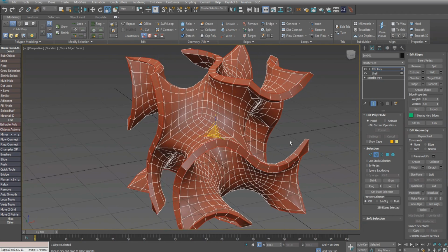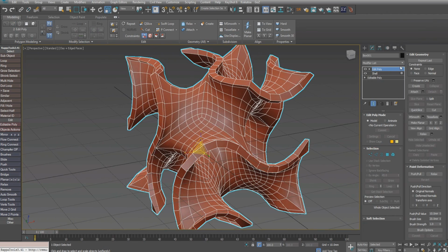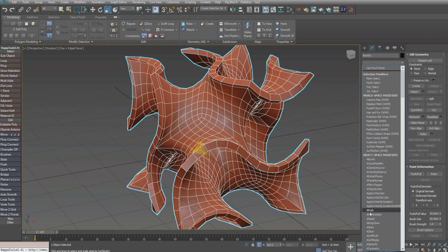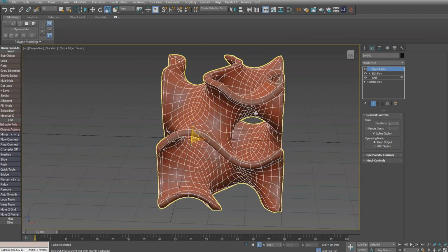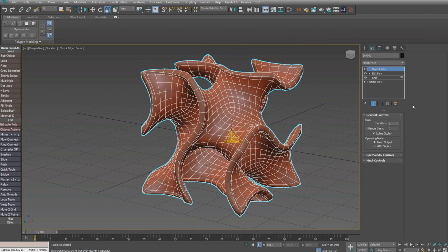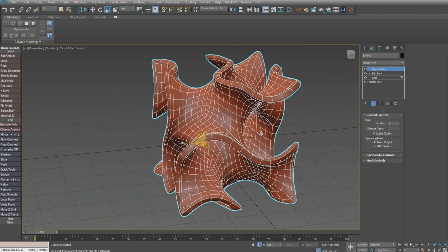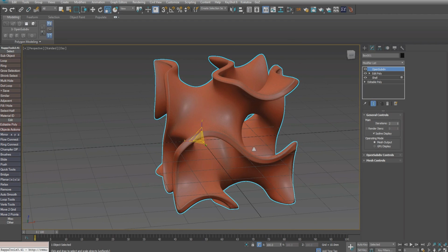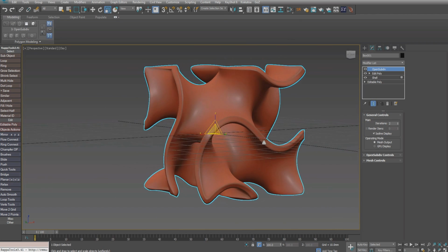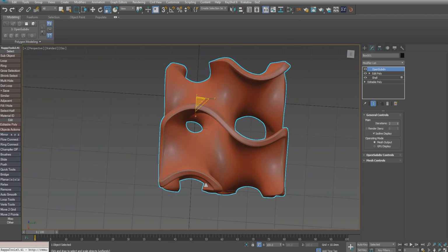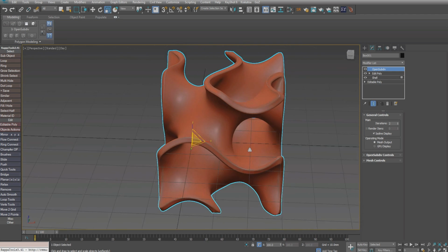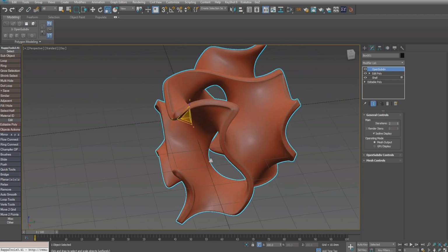And that'll give us a nice crease just on these border edges for when I add an open subdiv modifier here. And you can see that that's creased those edges without any additional topology. And I'll give it 2 iterations if I'm going to use this object for 3D printing. If I export this for 3D printing, I'll need about 2 iterations for sufficient density. Okay.